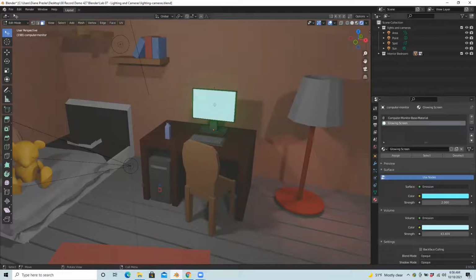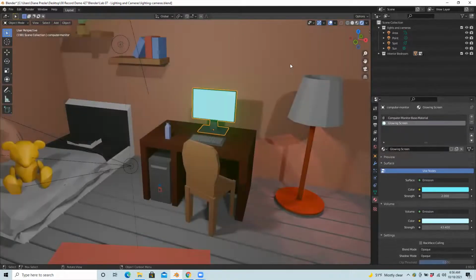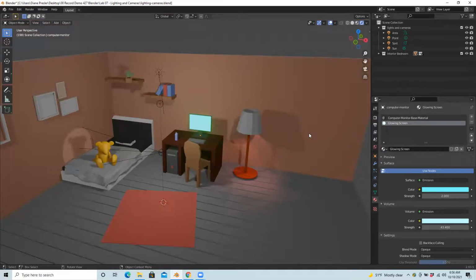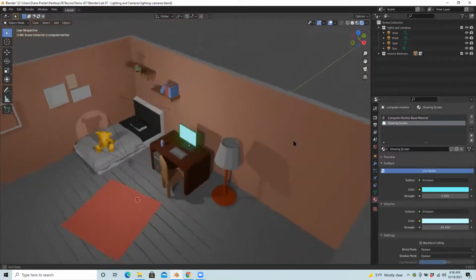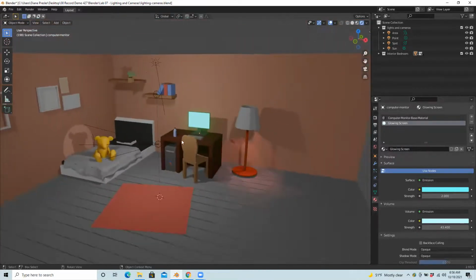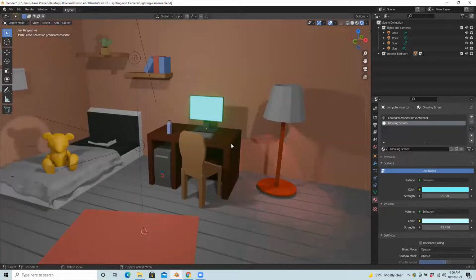And then that's it. I'm finished applying that material to that section, so I can switch back to object mode, and maybe I'll deselect by either clicking a blank area, or I can use the shortcut Alt A or Option A to deselect everything. So yeah, it's pretty interesting. It's actually glowing, so you can see the color around it in the rendered view, and it's affecting neighboring objects that are pretty close to it. It's not as strong as these other lights.